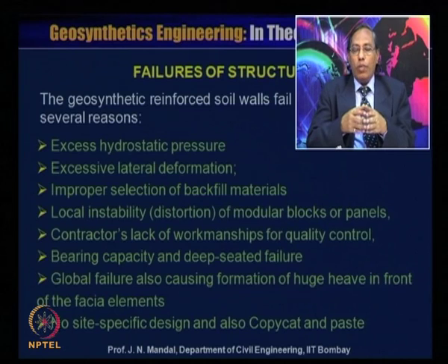And most of the time you also must avoid deep-seated failure or global stability failure. So this one has to be taken care of, and you check what will be the factor of safety against global stability or deep-seated failure stability.